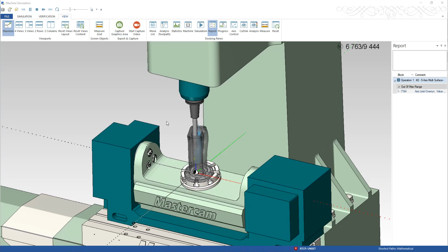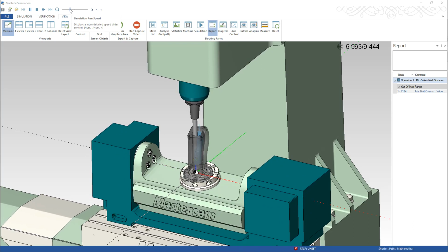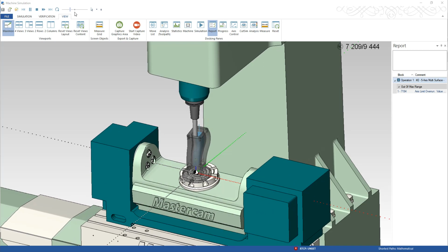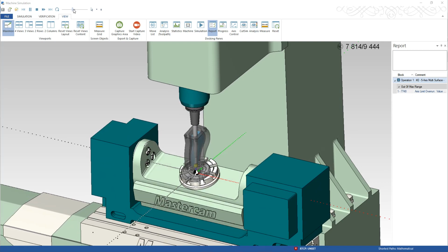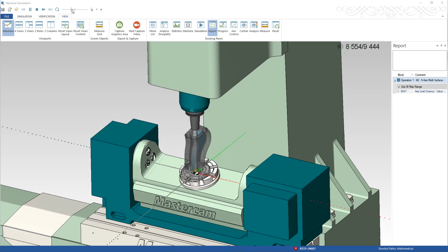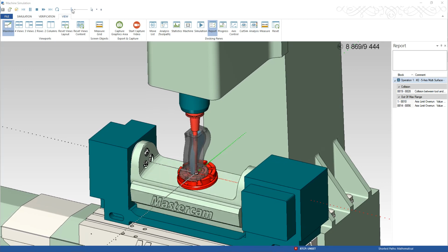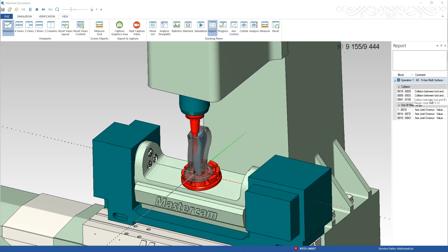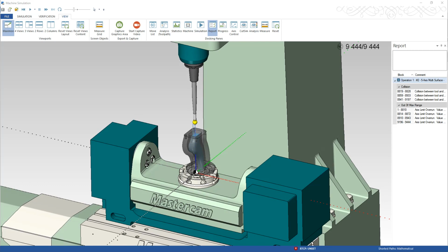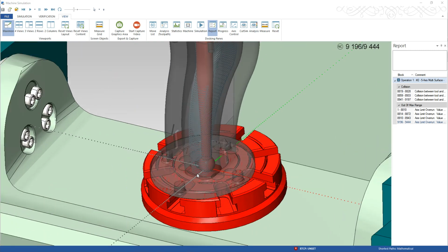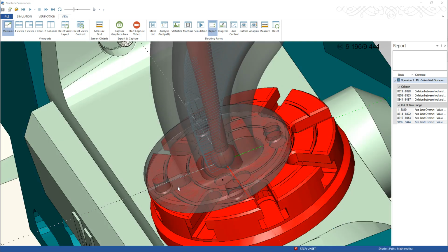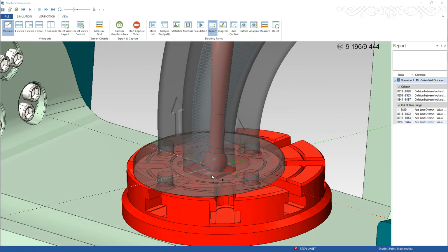And as I get down towards the bottom of the toolpath, you'll see that over here in my collision report, it'll actually tell me. I'm going to speed it up a little bit here as we go through. Looks really, really cool. And I get down towards the bottom, and it says I've collided the tool into the table. So I would have to do something to put this up on a fixture plate to keep me from running into the table and marring up my top fixture plate.